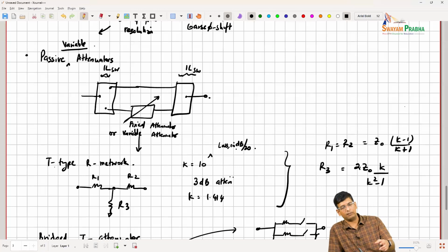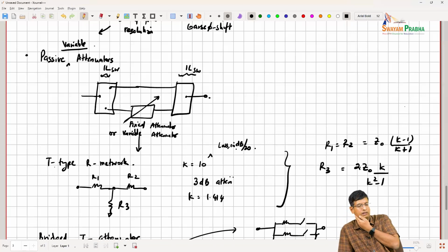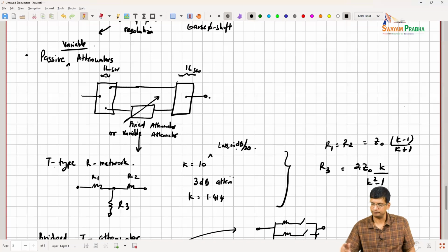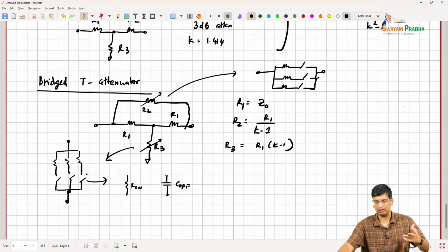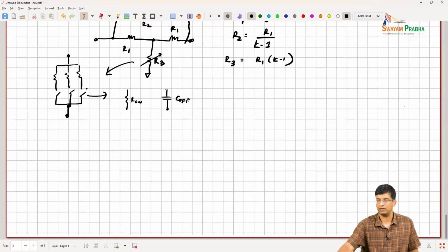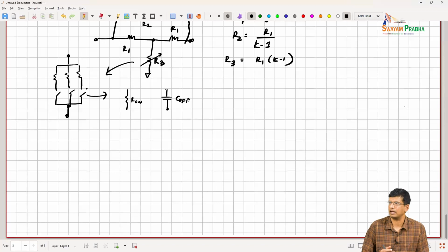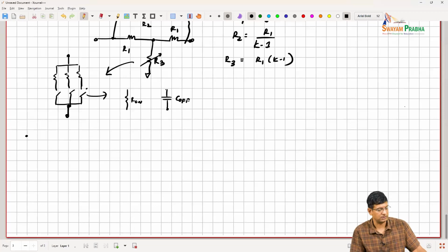And typically, if you try to make multiple stages of this, you have to pay that penalty as well, right? You can find out in your technology what the order of magnitude switch losses are by taking a single switch and simulating that, and that basically helps you make the decision on appropriate choice of topologies.